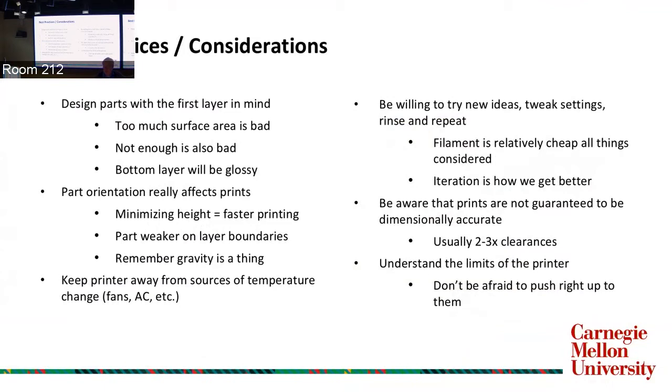This is less of a thing you have to worry about, but if you do have your own printer at home, don't put it next to the heater or the air conditioner. The thermals that are going on in there are fairly sensitive to outside forces. So if it's cold and you've got a window open, don't print next to the window. I mean, it gets tempting because sometimes these things smell when they print, especially ABS, but you want to try to take care of that.